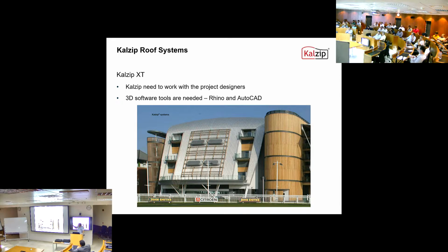Also, we use Rhinoceros software, which is a surface modeler. A lot of architects use the same software, so we collaborate with the architects to work out the optimum performance, and then with the installation partners, if they have the Rhinoceros software as well, we can share the models and the information, and we come up with the best solution to achieve the geometry. So there's a lot of support through the process with complex geometry schemes. And as Tony said, we can visit site when you're doing the installation to make sure you understand how the system goes together, where the clips go.